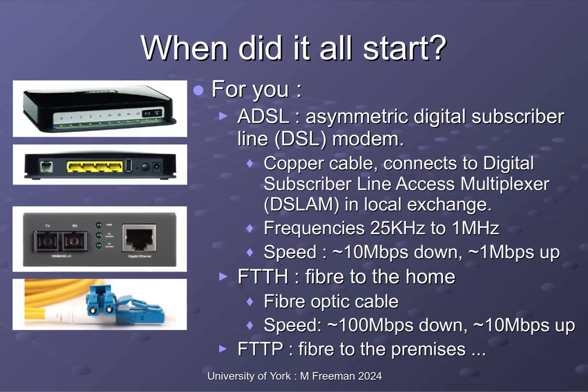So the question then arises, how do we increase our bitrate? So how do we get more bits per second down those copper wires? And the solution is to move the exchange closer to your house. So if you can shorten that distance between your home and the exchange, you can start to make use of those higher frequencies. So we start to see the rollout of digital subscriber lines, so DSL modems.